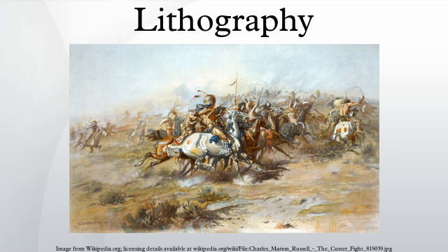In addition to these commercially well-established techniques, a large number of promising microlithographic and nanolithographic technologies exist or are being developed, including nano-imprint lithography, interference lithography, X-ray lithography, extreme ultraviolet lithography, magnetolithography and scanning probe lithography. Some of these new techniques have been used successfully for small-scale commercial and important research applications.